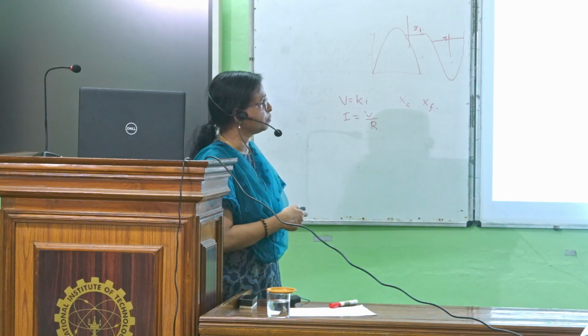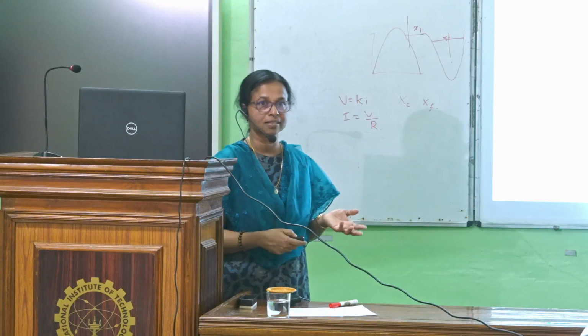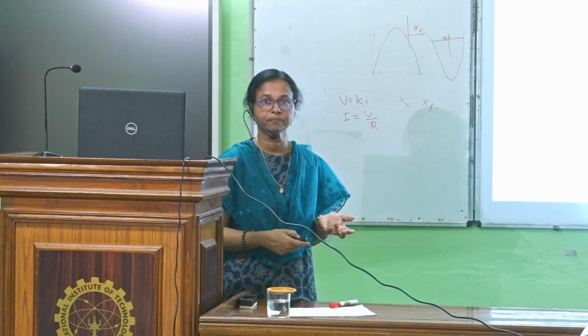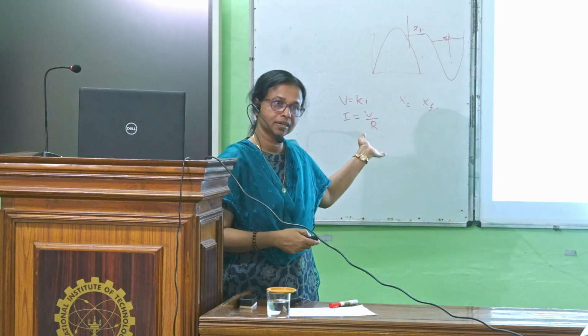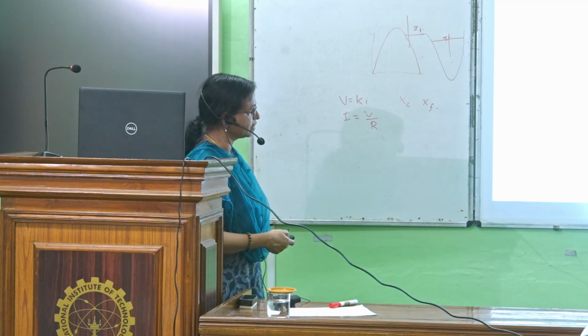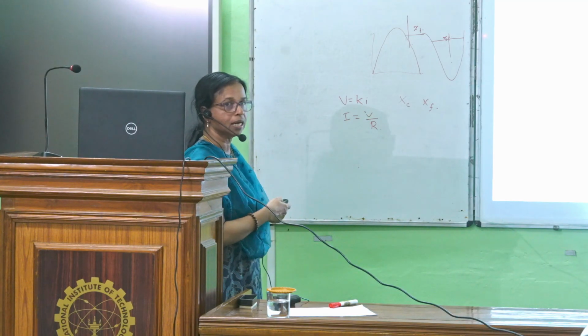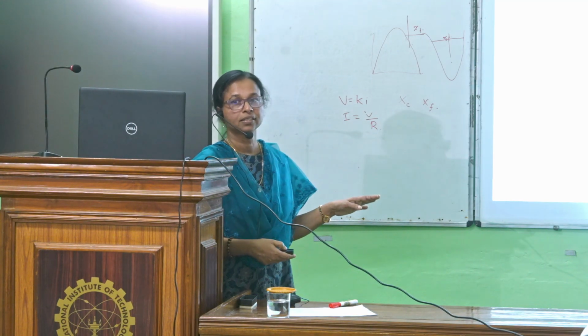So this will go up to the upstream side. This is what you are doing in HEC-RAS, finding out the water levels, the Y2 or any other sections. So for different sections, first we will consider the two sections, find out Y2 here, then Y3 here. Like that it will go up to the upstream side. So this is the basis of the HEC-RAS model.